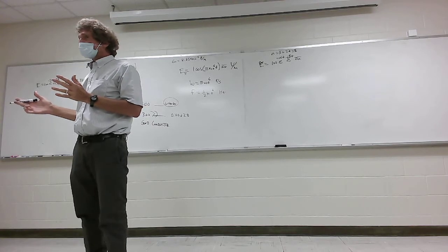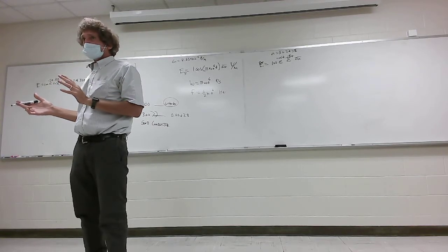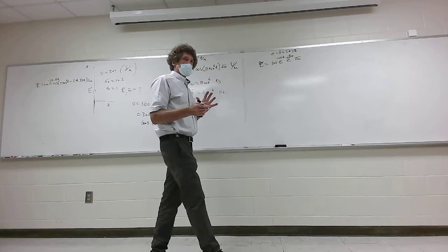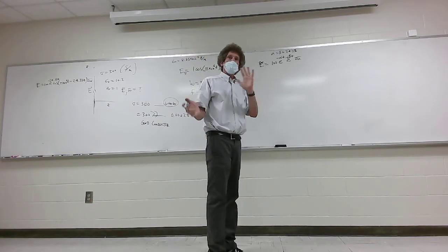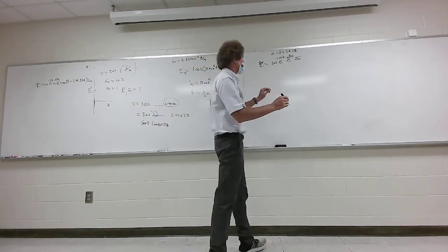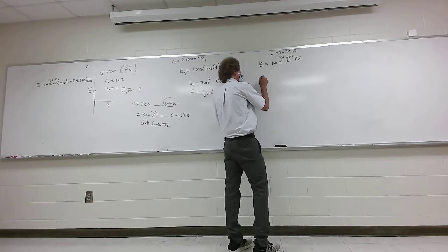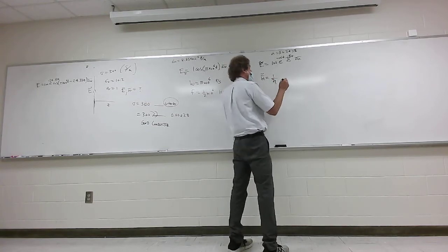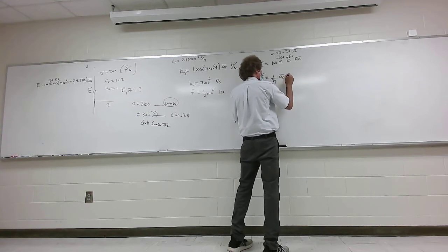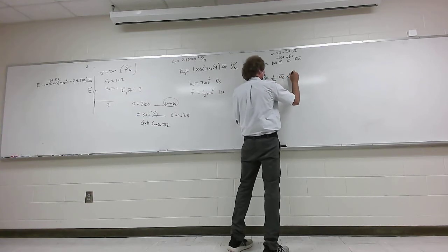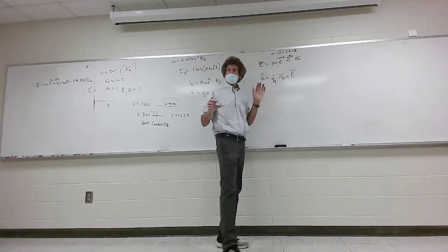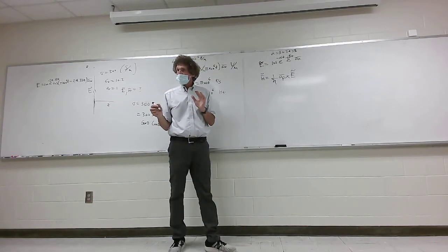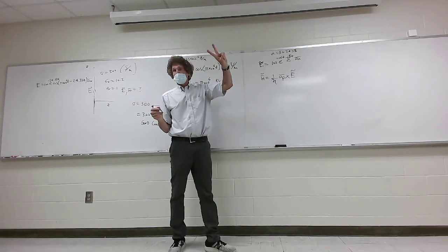Please watch this. This gets a little bit confusing if you're not careful. I gave you a couple equations that relate E to H and H to E for plane waves. Y'all remember, if you wanted the H field, if it was a plane wave, in the phasor form it would be 1/eta, right? And then the unit vector in the direction of propagation crossed into the E field, right? There are two equations, that's one of them.